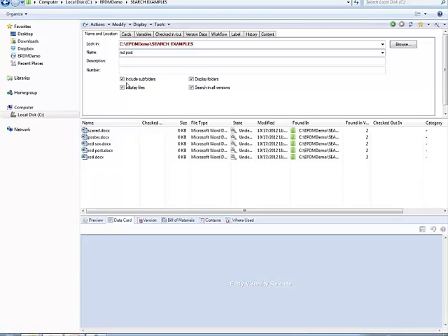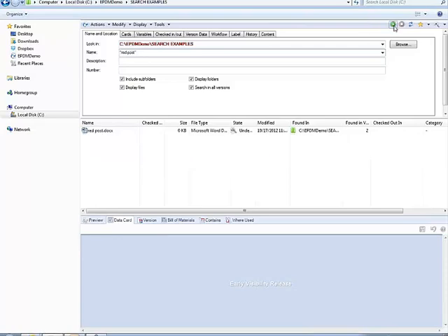If I wanted to look for this phrase specifically in the file name, and this is strictly for use in the file name search field, I can put double quotes around the phrase that I'm looking for, and it will return the single result red post that matches that phrase exactly. This would also be similar if I said red star post.